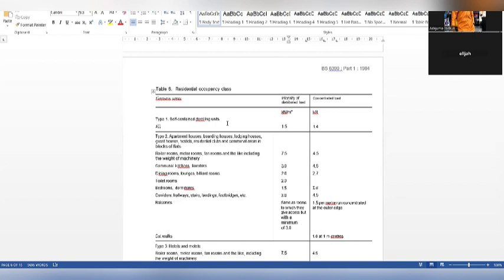You can't compare the weight to that of a normal structure where you just have your chair and your table and all of this. So imagine if an engineer just misplaced the two of them and used 1.5 kilonewton per meter to design a boiler room. Now you discover that even though the building will be standing, as soon as they load the building with the required equipment, then problem comes, collapse here and there, you know. So that's why it's important to use the right live load, the right imposed load for your building.